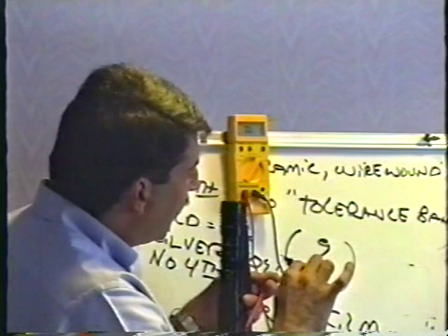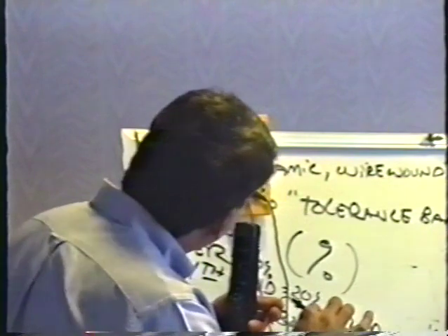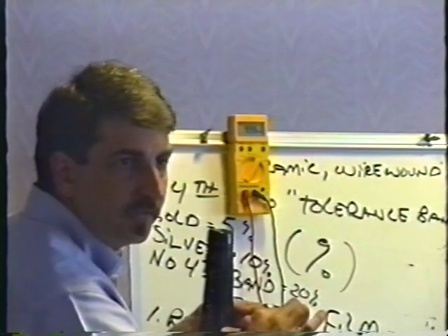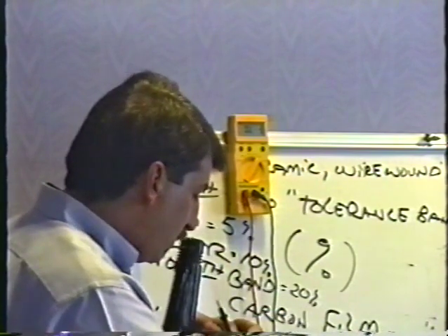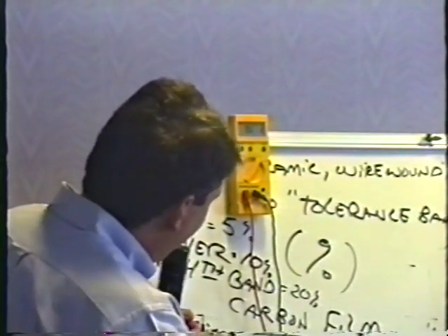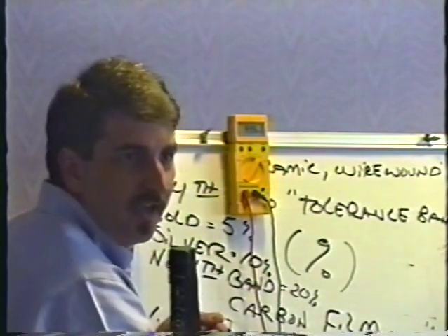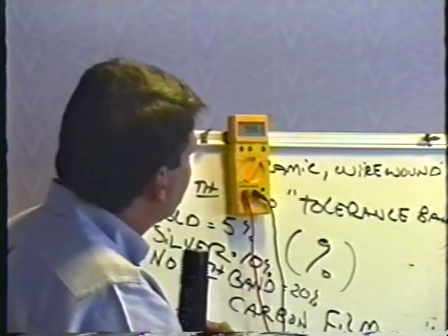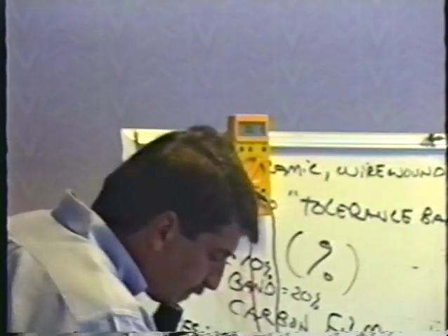If I'm just holding the meter lead, touch the other meter lead to the resistor, my meter says 0.996K, or about 1,000 K. So this is a 1 megohm resistor, really, is what it is. So presumably this is brown, black, green. What? Wait a minute. Which it isn't. Let me see what. Oh, 0.9K. I'm sorry, almost 1K. It's a 1K. It's 0.9K. Sorry, I misread it. See what I mean about that little K up there? It kind of freaks me out. It's almost 1K. This should be a 1K, which it is because it's brown, black, red, which is a common resistor.